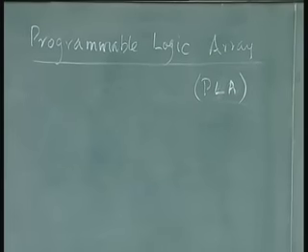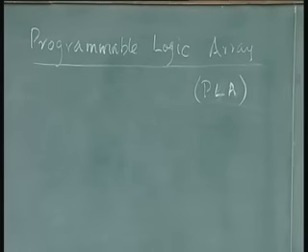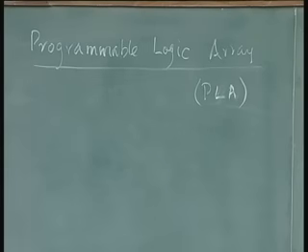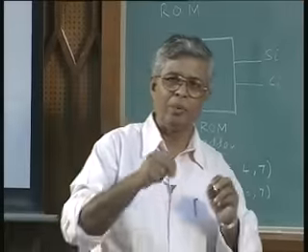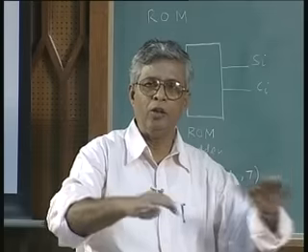Now, the difference between a ROM approach and a PLA approach is simple. Again, it is programmable. In the sense, I should be able to change my connectivity either for making minor changes or because I want to correct a design bug, or I make a minor change in my solution, or totally remove the application and put in a new application.